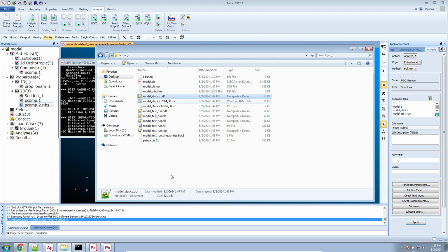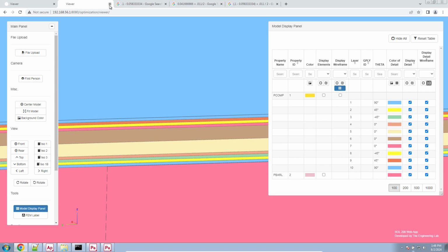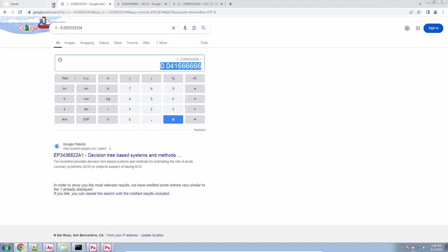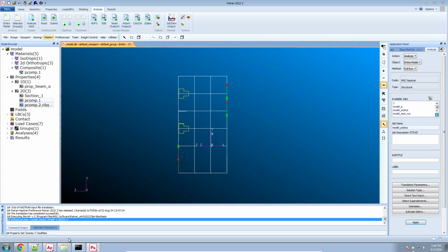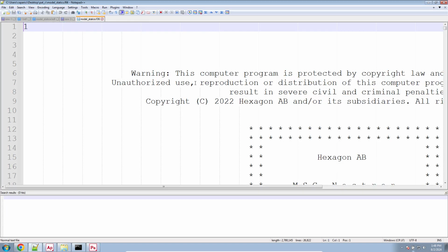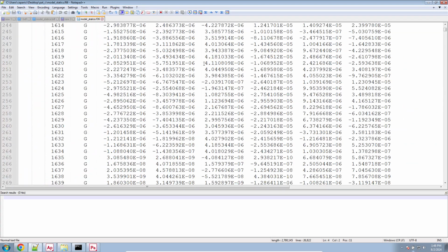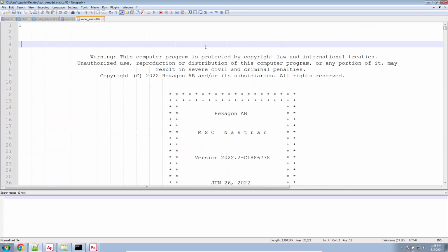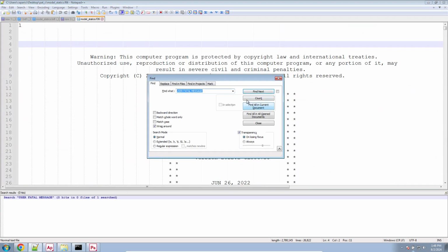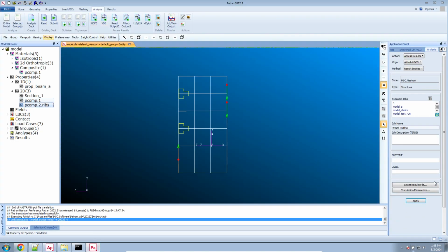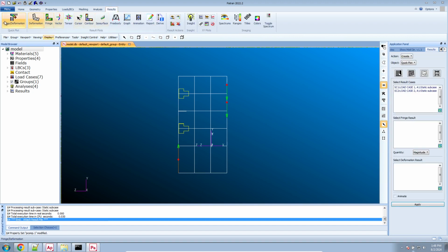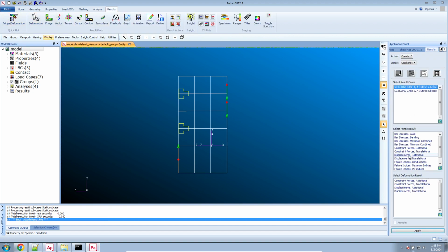And this one's taking a little longer. I think since I have so many things open up in this viewer or in this virtual machine, it's slowing down my machine. So let's go ahead and close some of these objects. And let's go ahead and open the F06 file. And remember, always look for any user fatal messages. You never want this message. There are no messages like that. Let's go ahead and import the HDF5 file. Let's look at maybe some results here. Let's look at a quick displacement results.